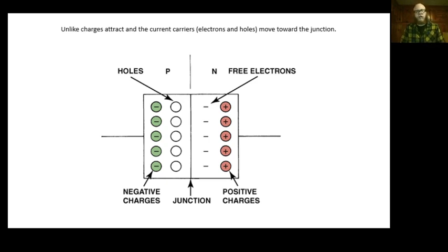We'll talk about the way that our meters can test a diode to see if it's any good or not. And this works for regular diodes and LEDs as well. When our meter does a resistance measurement, if it's just doing an ohms measurement, it only puts out about 0.3 of a volt, so 0.3 volts. That's not enough to push current past this margin, past this junction. Think of it like a wall. If I tried a little bit to climb over a wall, I'm not going to climb over the wall. If I try a little bit harder, well, depending on how high that wall is, maybe I'll get over there.